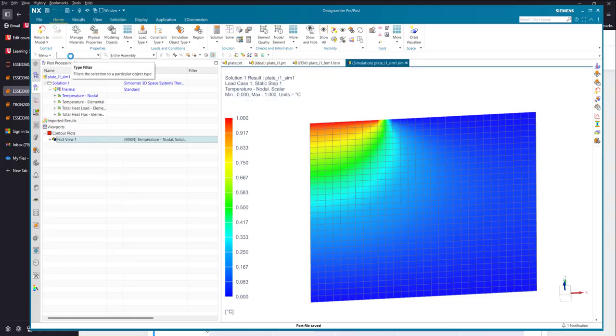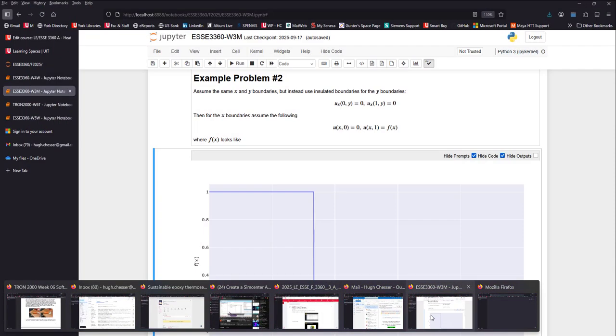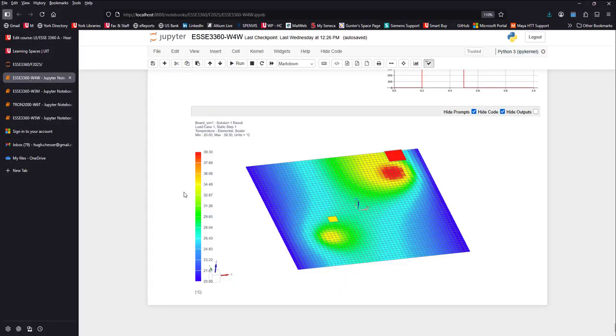Now, the other more fairly powerful feature of NX is this ability to create, between surfaces that are actually not touching, we can still create thermal conductances between different bodies. And so this is a very powerful technique. If I move these surfaces, which I'll demonstrate, then we can just simply rerun the analysis and it can be repeated for different locations. So let's go ahead and see that in action.